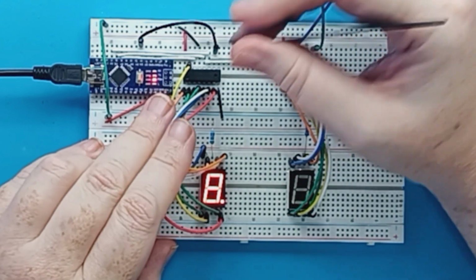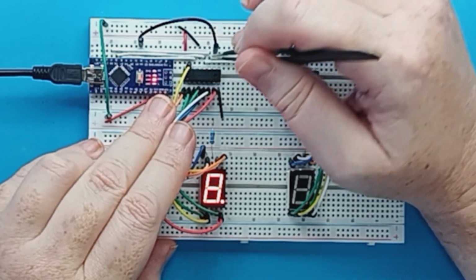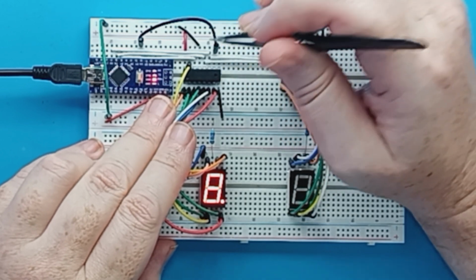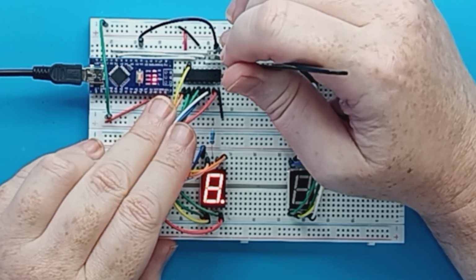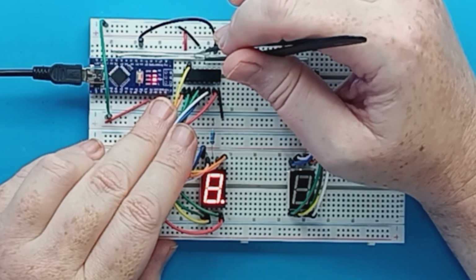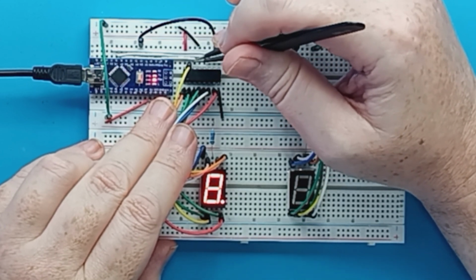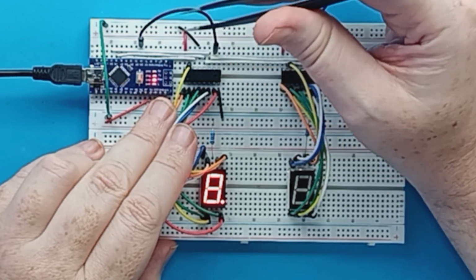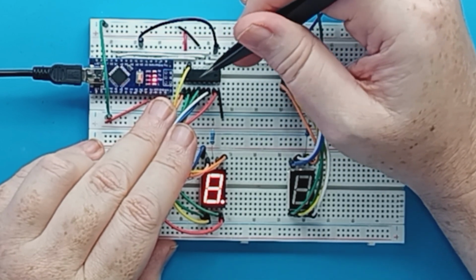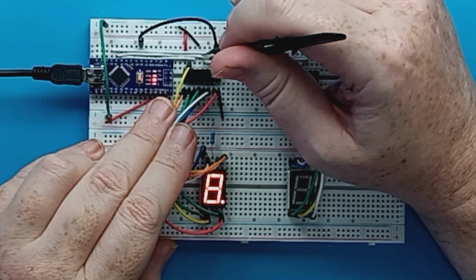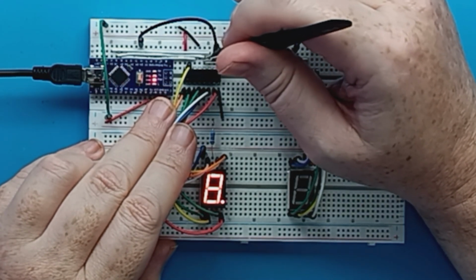So anyway, how does this work? We have the serial clock, which on a rising edge reads in the data, whatever's set on the serial pin. That gets into the internal register, but it doesn't get set to the output until we have a rising edge on the R clock line.